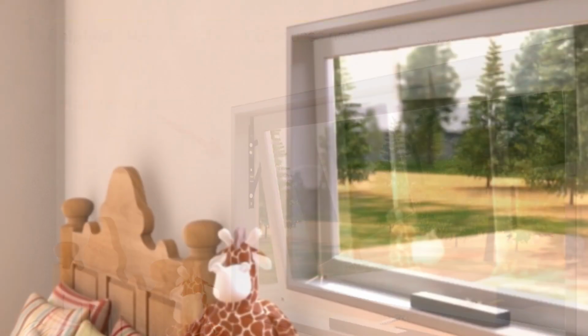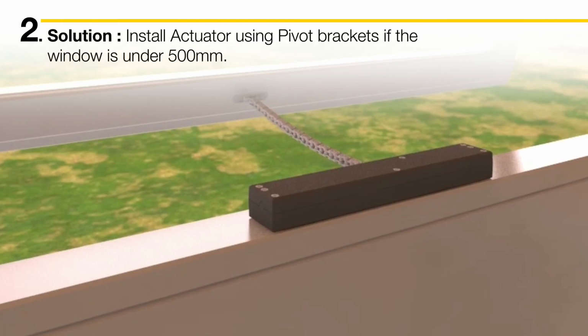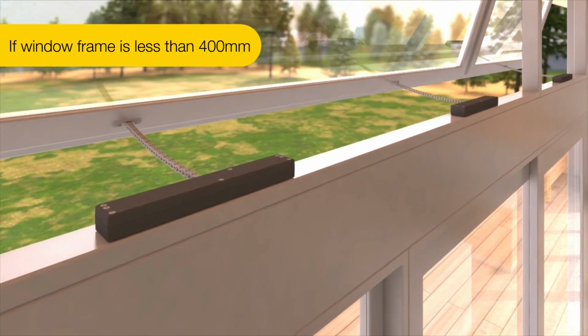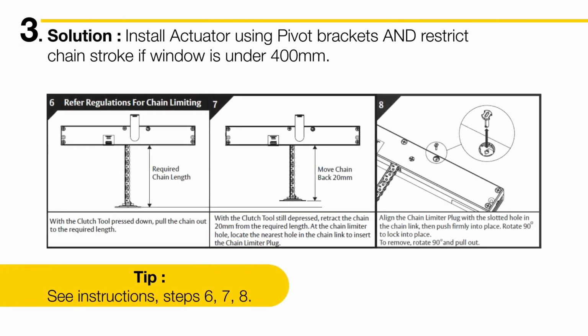If there are no obstructions, check the windows are using non-friction stays. It could also be that the window is too short for the chain stroke. If the window sash is shorter than 500 millimeters, then the actuator must be installed using the pivot brackets. If the window sash is shorter than 400 millimeters, then you must use the pivot brackets and also restrict the stroke of the chain to 200 millimeters. See steps 6, 7 and 8 in the install instructions for details on restricting the actuator chain stroke, or check with the installer if this has been done.